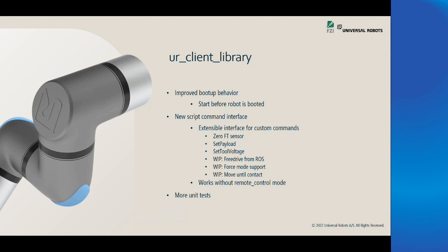Then a couple of really new cool things: we have introduced a command interface. Especially for E-series robots, there had been the trouble that if you want to send some commands to the robot, like setting IOs or sending custom script commands or stuff like that, the robot needs to be in remote control mode. This has been causing some issues with people because it's not that obvious at first glance. So this is something we try to improve as a user experience.